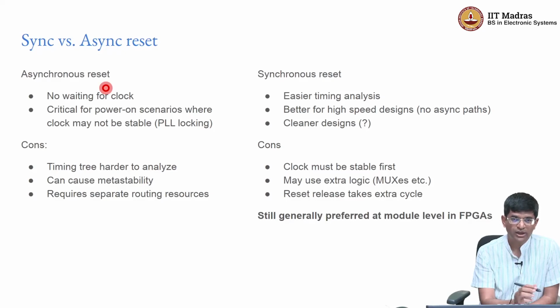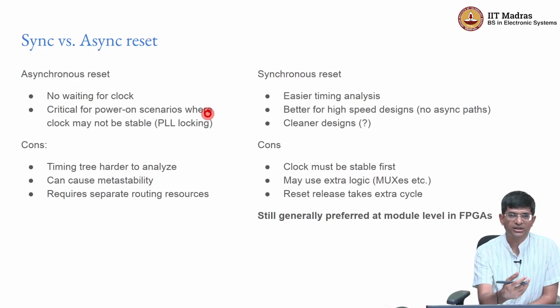Now, the important point is that this asynchronous reset is usually critical for power on scenarios, right? Why is that? Because the way actual circuits work is that it's not that as soon as you switch on the system there is a clock and the system just starts working. The clock is also an electrical circuit which takes a little bit of time to ramp up and stabilize and actually get to the correct frequency and have the correct square wave behavior that we expect from it.